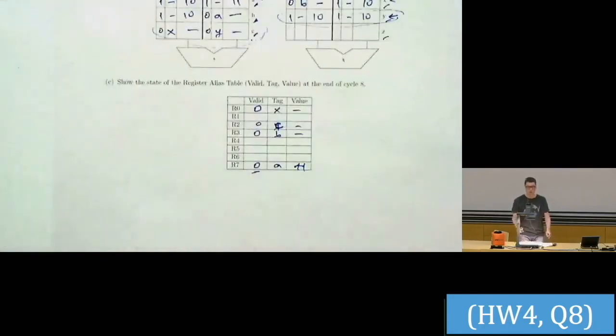Yeah. Would in this case then make sense to fill the register alias table from the bottom up based on the reservation stations? Because then we could never run into an issue where we write something in the register alias table and suddenly figure out, oh, there's a new rule value. Would it make sense to write it from the bottom up?